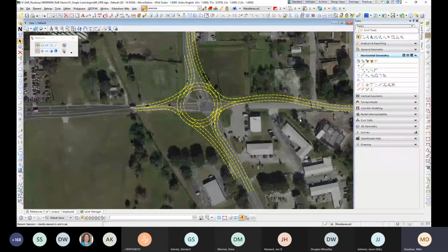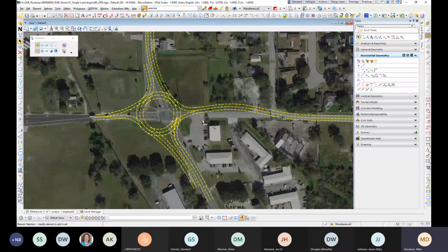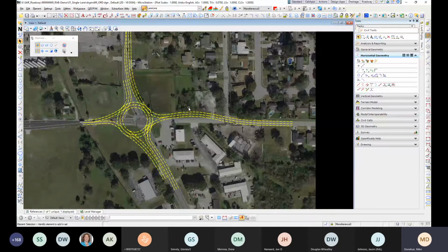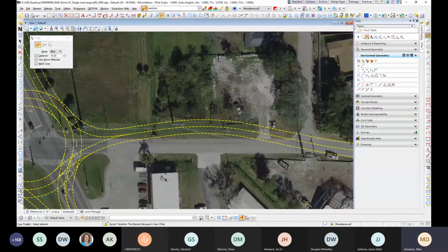And that's really the idea behind leveraging this technology to set all that up. But once you have that technology, offsetting curb and gutter lines and drawing up your sidewalk and all those things can become very cumbersome and time consuming using these elements, because just offsetting this line with a MicroStation command to move parallel or copy parallel, it doesn't work. It doesn't recognize it as a standard MicroStation line. So you're not going to be able to just offset these for 1.5 feet for a face of curb line or 2 feet for a back of curb line.